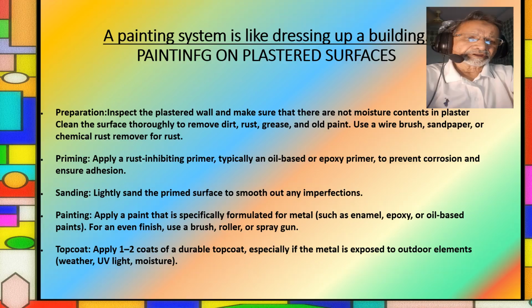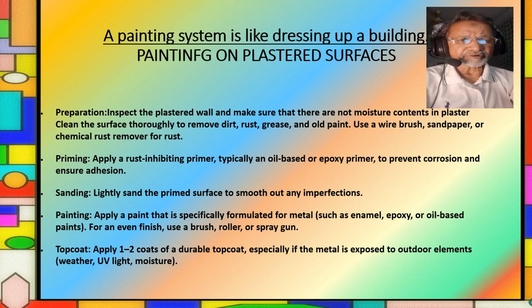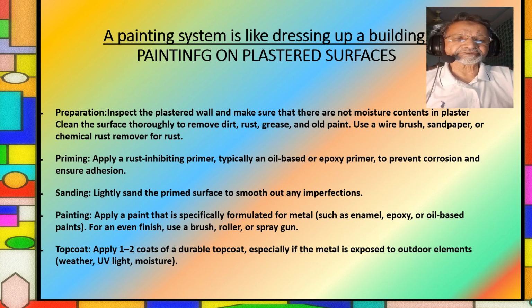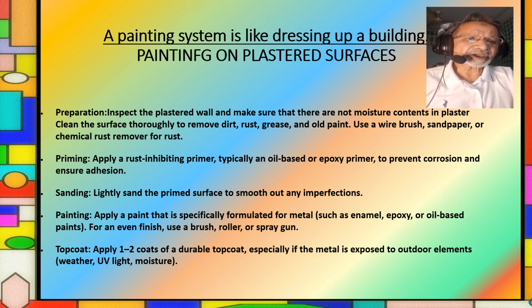Thank you very much. Dear engineers and other viewers, regarding the painting of freshly plastered surfaces, this is slide number 5. After the completion of plaster, it should be cured for a minimum of 7 days and left for drying after the curing period is over. To start with painting, the new plastered surface is to be thoroughly checked for zero presence of moisture.